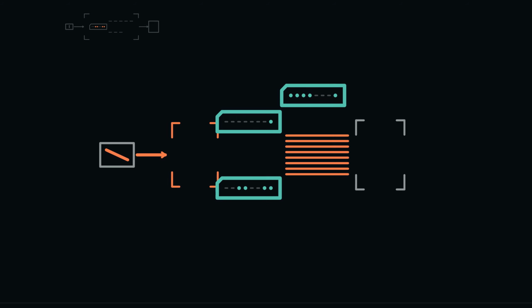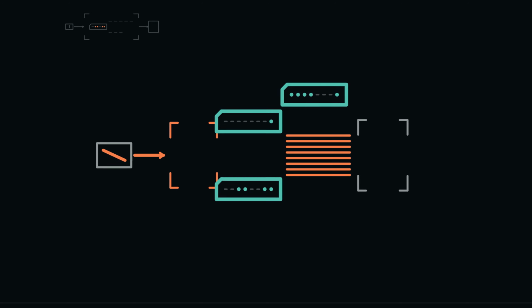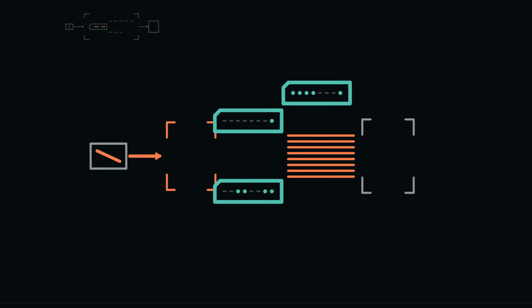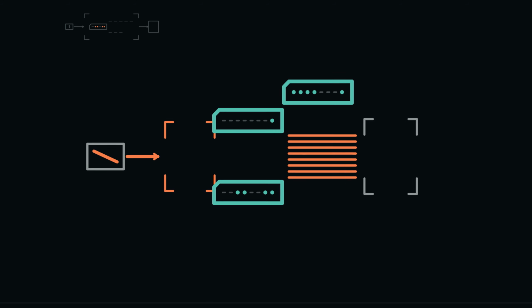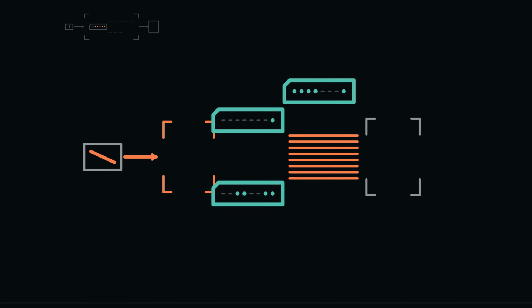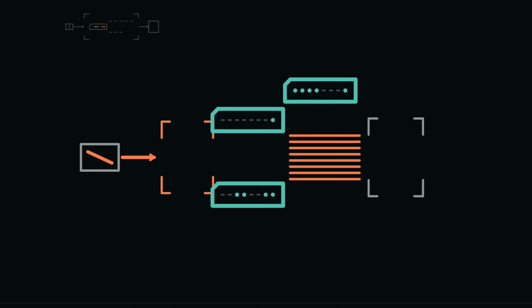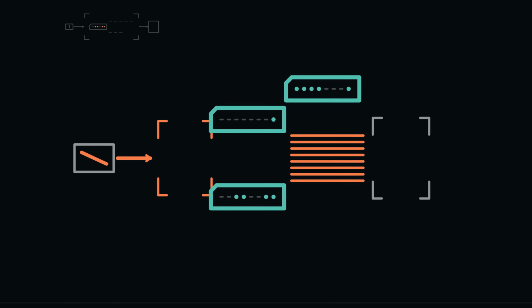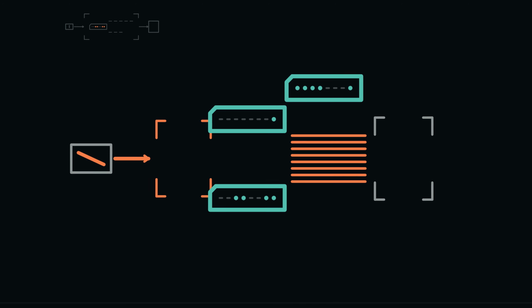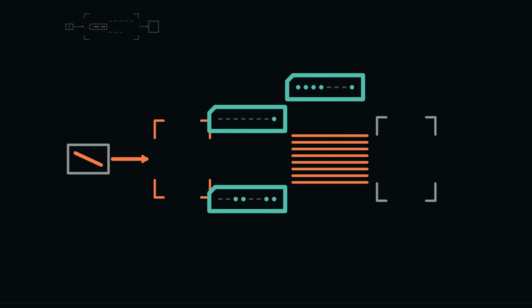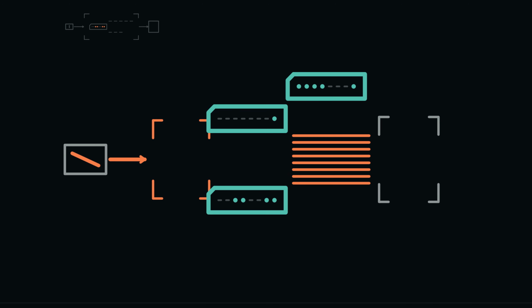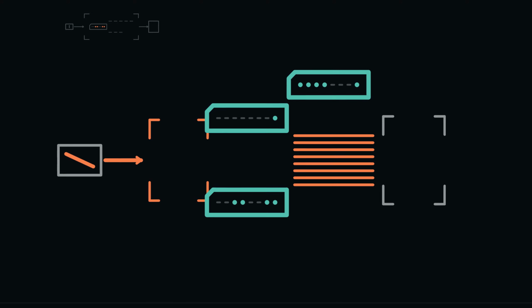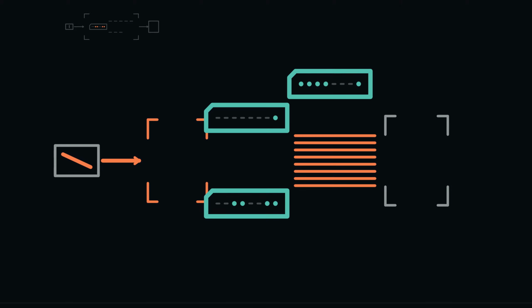The display side has its own direction. In SE8 version 1, reading display status returns 1, meaning the adapter is ready to accept a byte. Writing to display data appends the supplied byte to the device's output sequence. A load cannot accidentally draw, and a store to ordinary RAM cannot accidentally reach the display. Both the operation and the selected address must match the contract. Reserved device addresses fault so that an undefined path cannot be mistaken for a harmless no operation.